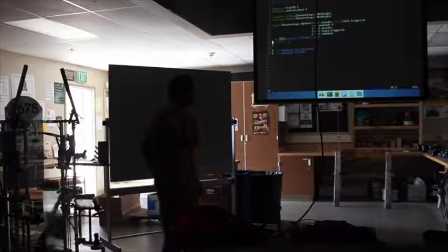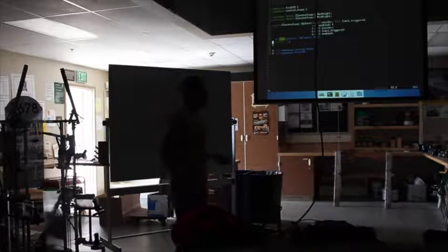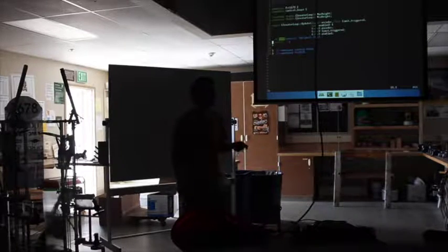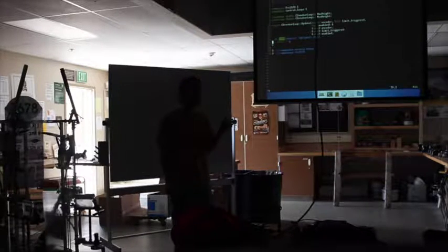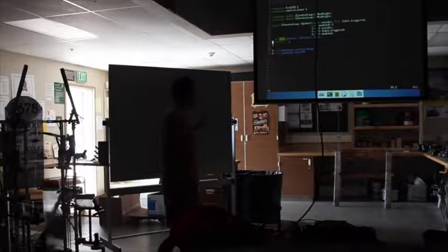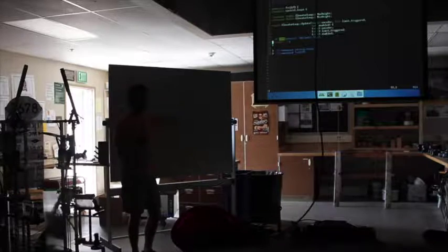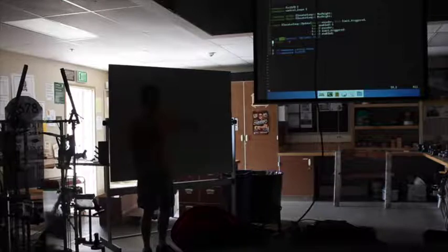Because you can't zero, at least on our robots, if it's an active zero, you can't zero till you're enabled. And what you also want is to design your software so your user can't mess it up. So if the driver doesn't hit the magic set of 3 buttons to make the robot work, they don't always remember that. It's the heat of the moment. They're not going to remember to press these 3 buttons before they run the match. So we want to design software that's robust to these things and doesn't let the driver screw it up. So by putting it in here, the driver can ask for whatever he wants from the joysticks, and we will not let him do anything bad.